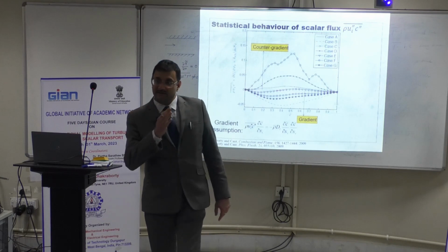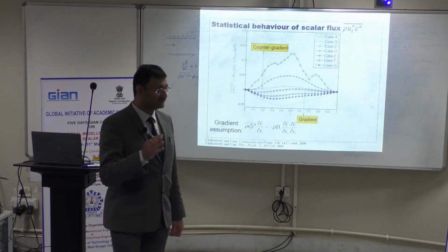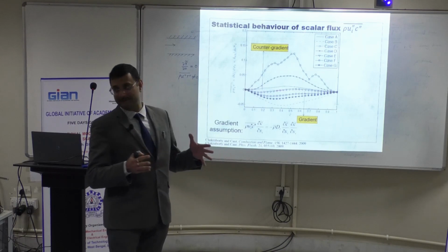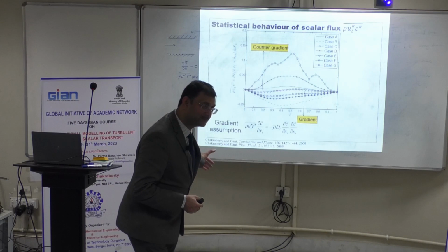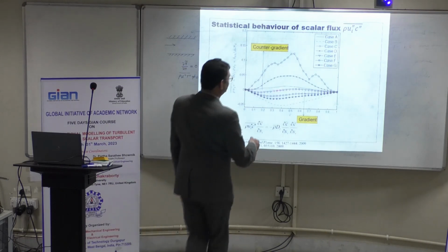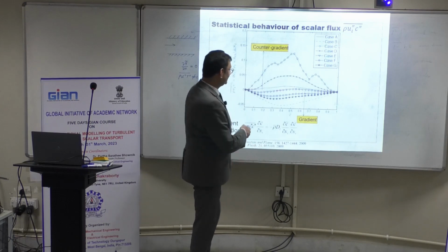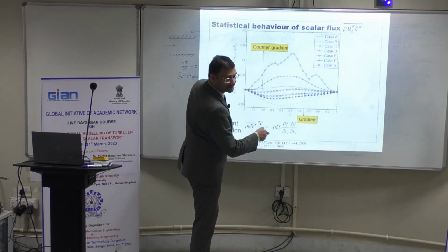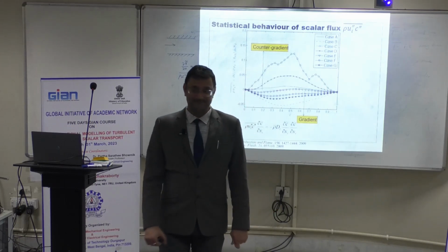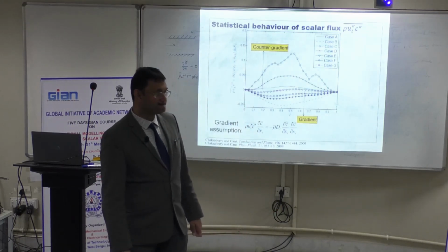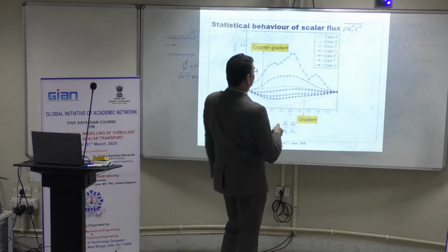Towards the unburned gas side, where the heat release effects are not strong, u prime effects are dominating, so it starts as a gradient transport. As it comes towards the reaction zone, heat release effects become strong. It actually goes through a transition and becomes counter gradient. Okay? Clear? Case F.